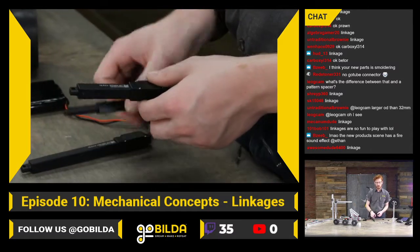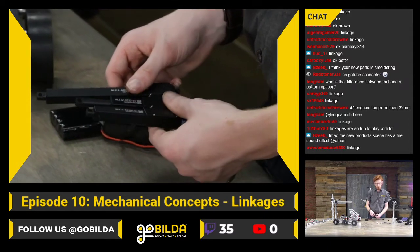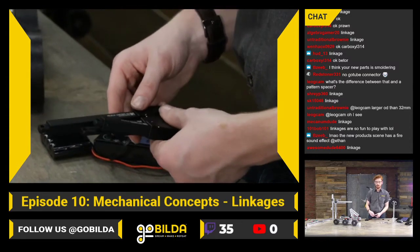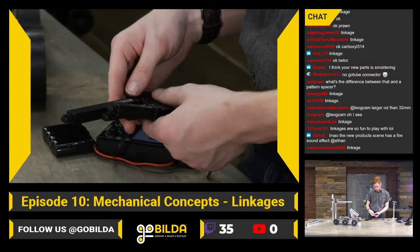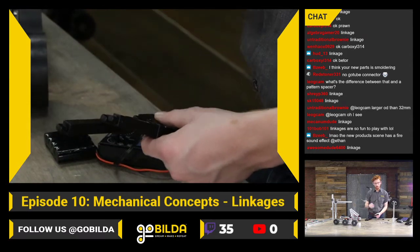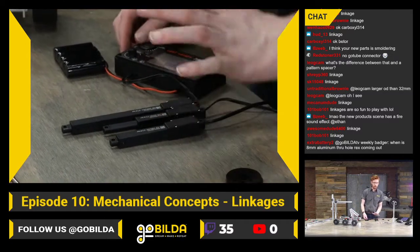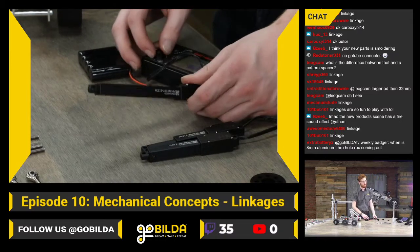They come in 3 sizes, and each size has 3 different ratios. So you get either 100 mil, 50 mil, or 30 mil of stroke. And within that, you can get 50 to 1, 380 to 1, or 250-something to 1, I can't remember the exact ratio there. But the speed to thrust ratio changes depending on the ratio that you go with and the amount of thrust that you need.